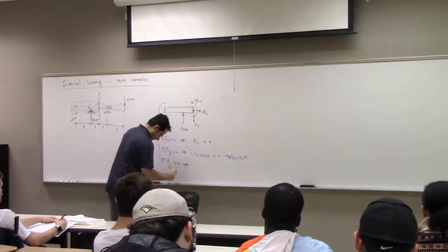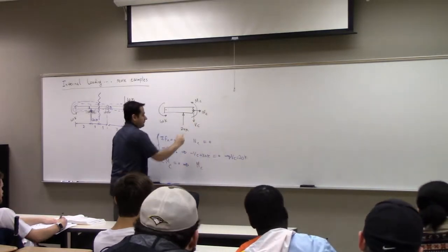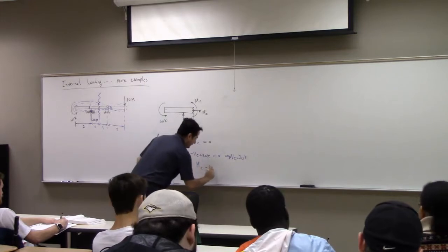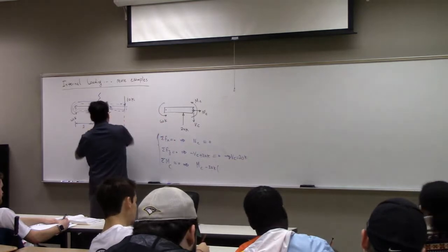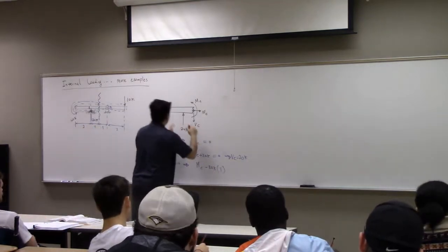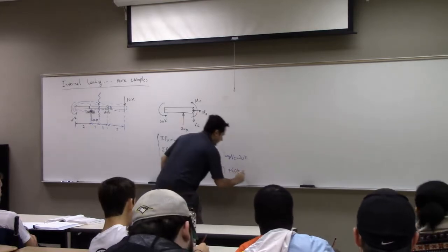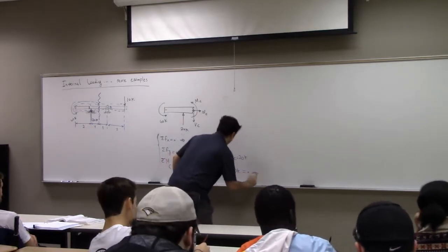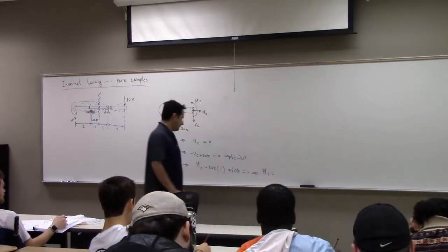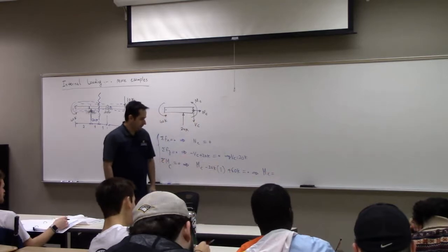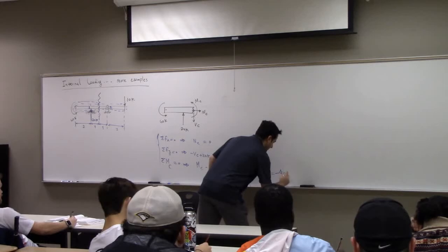Then you go and expand it. So you get positive MC, nothing comes from these two, negative 20K times this distance. This distance is 1. And then plus 60K is equal to 0. Solve for MC, so that's positive 40K, take it to the right, negative 40K.